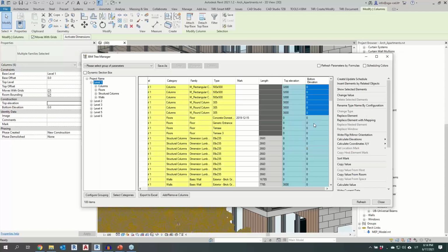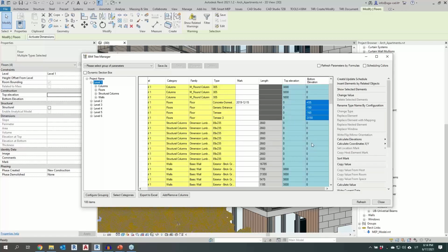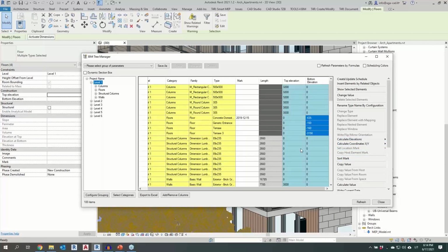project bottom. Well, yeah, of course, they stand on the 0 elevation, nothing new to write. For the floors, though, bottom elevation is a little bit different. So in this way, we can fill, maybe separate just walls, do filtration, and do at once for all the walls in the project, enter the values for the top or bottom. And it's easy as that.